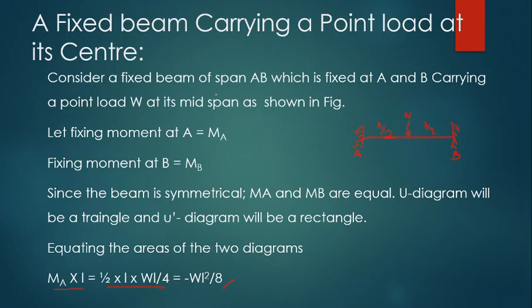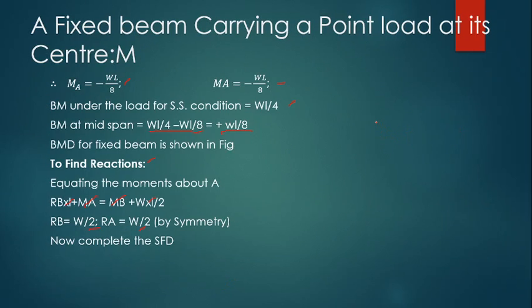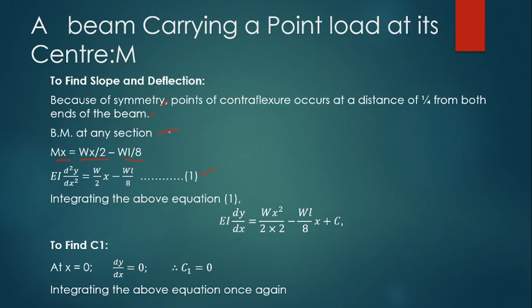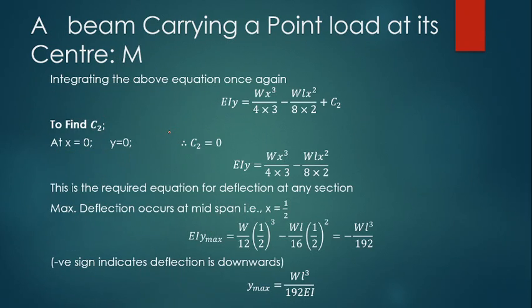We have also taken a first case: a fixed beam carrying a central point load W, length L, with fixed end moments at A and B. We have also drawn the shear force and bending moment diagram for the beam. And this is about slope and deflection.